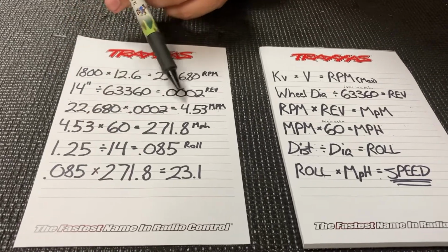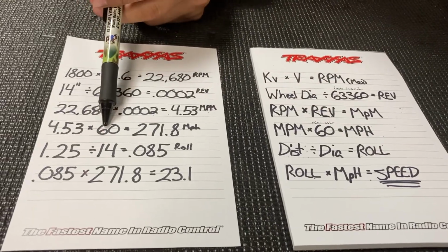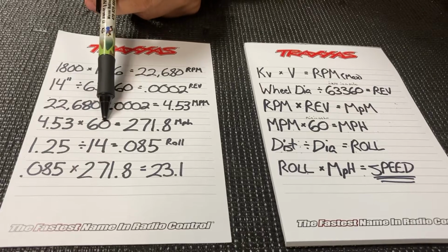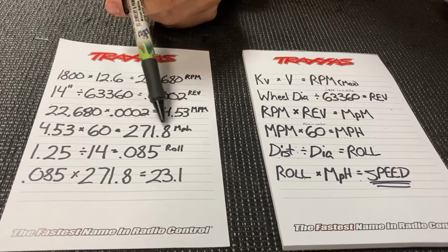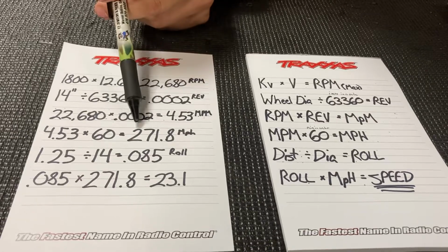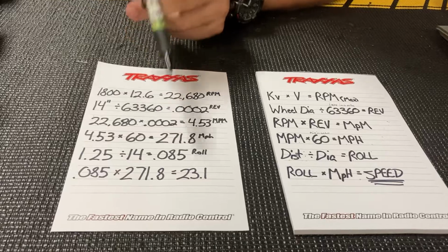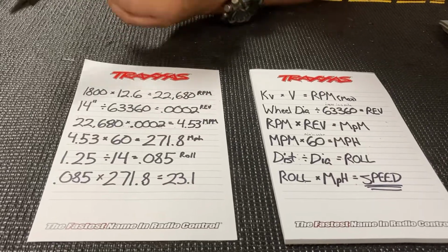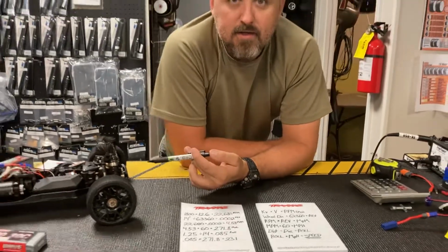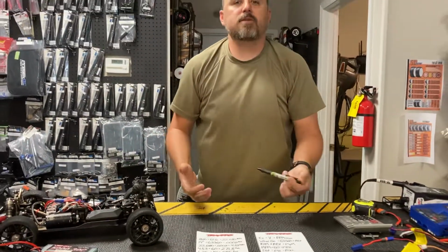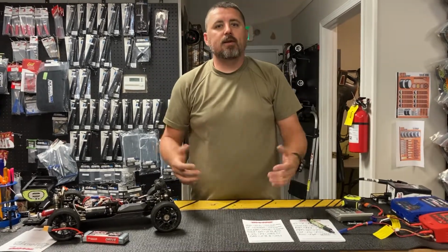All right. So the next thing we're going to do, we've got our miles per minute. We need to take our miles per minute and multiply that by 60 because there's 60 minutes in an hour. It's going to give us a speed of 271.8 miles per hour. I really wish my buggy went 271.8 miles per hour, but unfortunately it doesn't because of gear ratios. In this case, gear reductions. You have gear reduction between your pinion and your spur gear. You have gear reductions in your differentials, and so forth and so on. So what we've got to do is figure out what our gear reduction is.